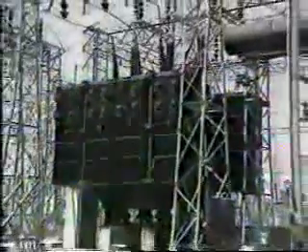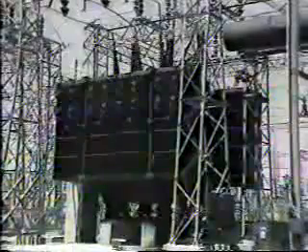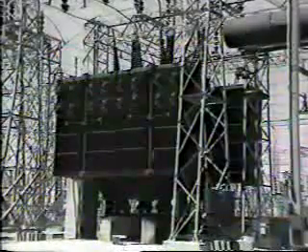Transformers are used all over the power system at all voltage levels and in sizes ranging from, say, 3 kVA up to 500 MVA. Generally, power transformers are three-phase. That is, the primary and secondary windings of each phase are wound on three legs of a common iron core, all immersed in the same tank of insulating oil. Single-phase transformers are also used, connected to form a three-phase bank. Any combination of Y or delta connections can be made to give the desired voltage levels and phase relationships.